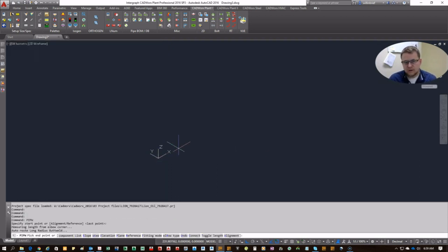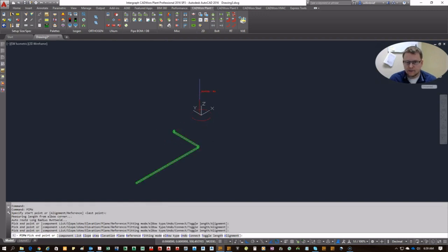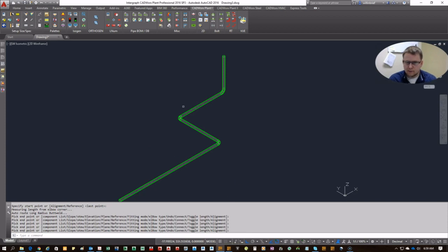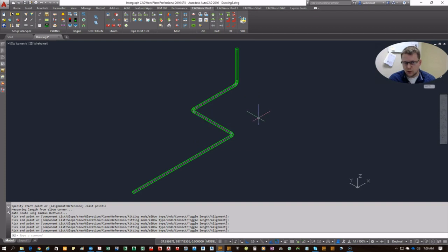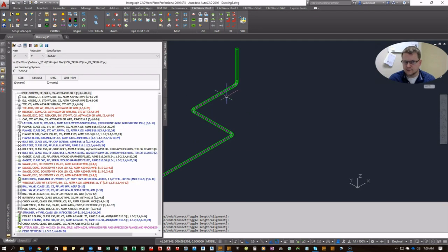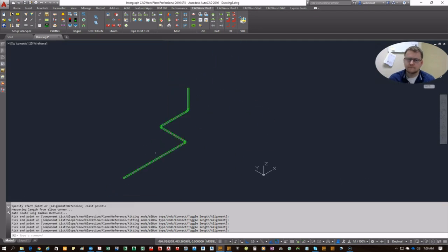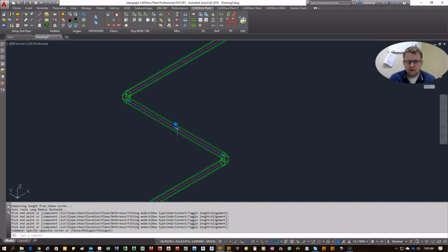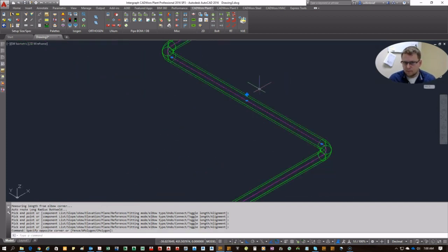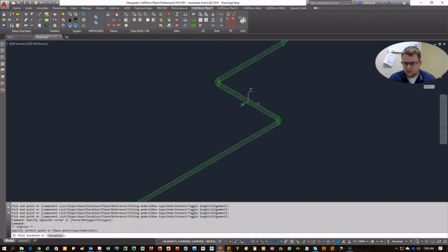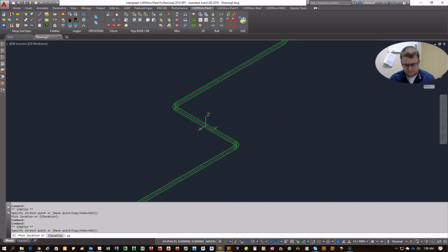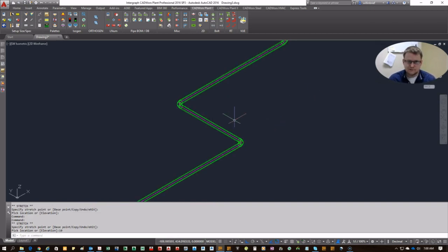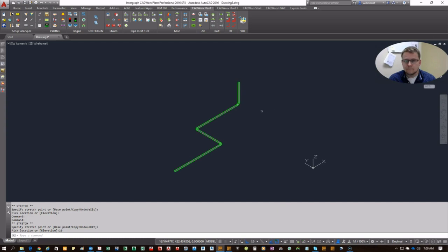Okay, now that you have a basic understanding of where you're going to come from for your components, you can go ahead and click on one of them and start modeling up. As you can see, automatically we have our pipe router built into the software. So once you select one object and you start putting it into the system, it wants to keep continuing on, which is awesome. If you click the middle node on pipes, you can also make size adjustments, moving it 10 feet, 10 inches in this case. So there you go, pipe router.